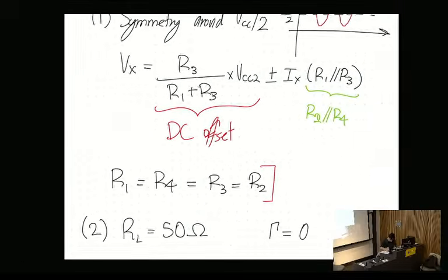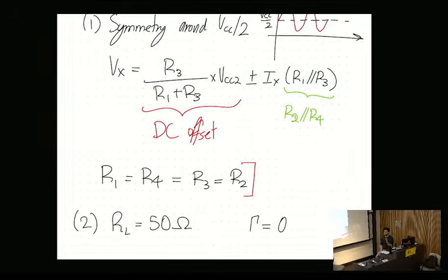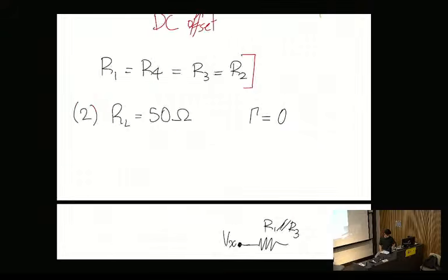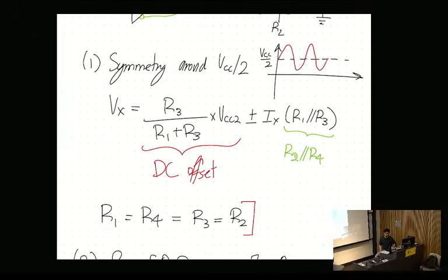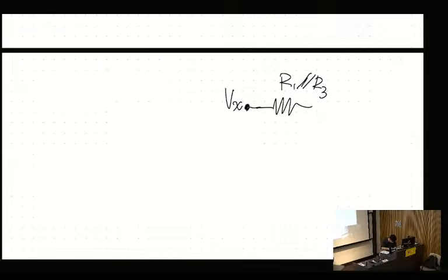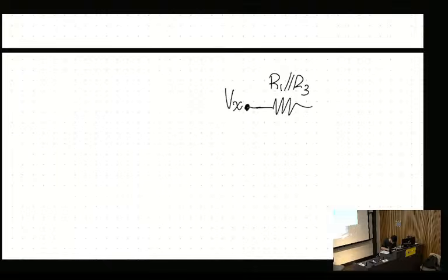The reason for that is, if we think back to quad 1, when you're looking for the resistance looking into a node, what can you do to voltage sources? You could short them, right? When you short them, you find that the resistance is effectively just the parallel combination. So where do you go from there? Yep. So what would the circuit look like? It would look like R1 in parallel with R3.